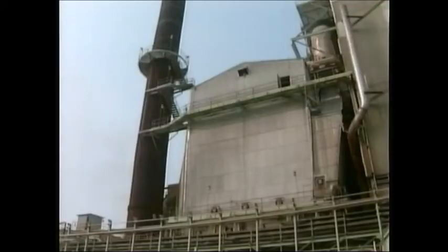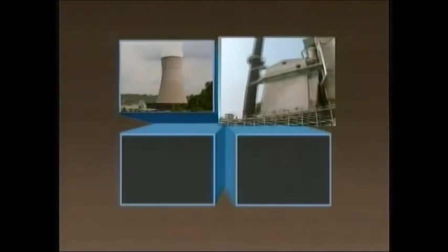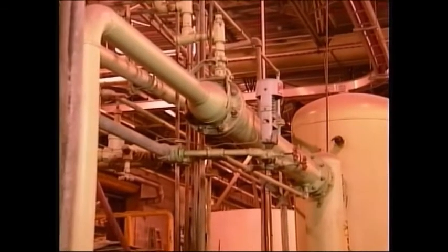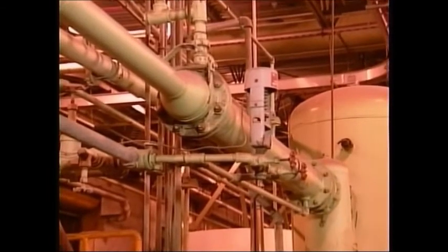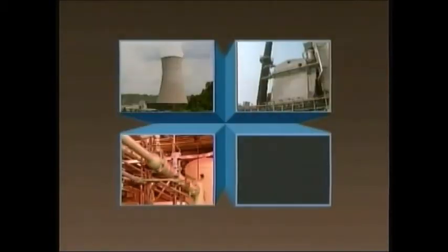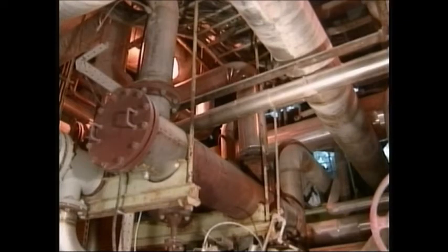Heat transfer, such as that occurring in this cooling tower, may be a part of many fluid processes. For example, heat is transferred in boilers, which use the heat from flame and combustion gases to generate steam. Heat exchangers like this one are used to cool process fluids. In this case, a cooling fluid absorbs heat from the process fluid as they flow through separate paths in the heat exchanger. Other heat exchangers are used to increase the temperature of process fluids.